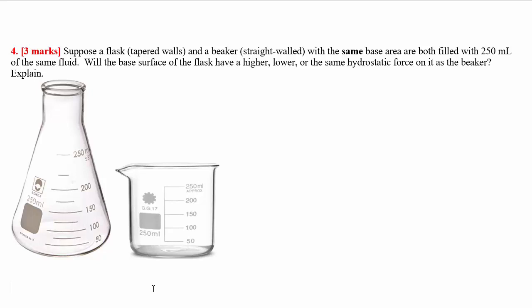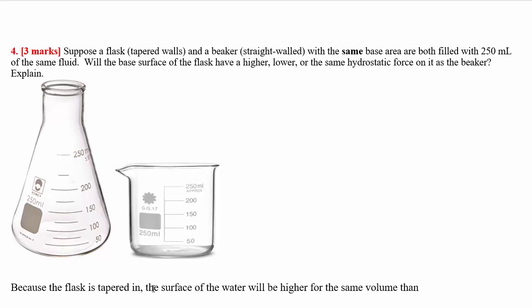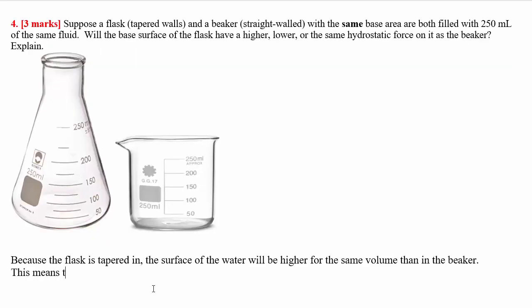So let's put that into words here. Because the flask is tapered in, the surface of the water will be higher for the same volume than in the beaker. This means the hydrostatic pressure on the bottom surface of the flask will be larger.